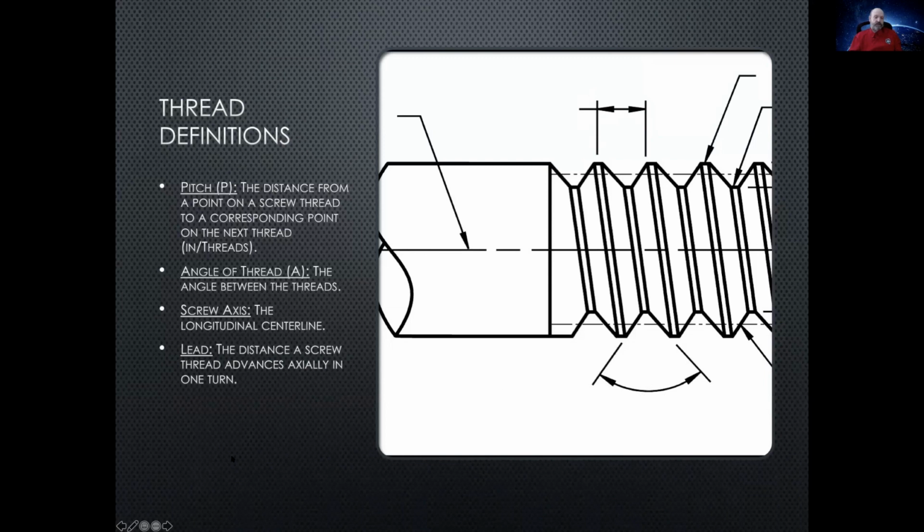So in industry, we used to have to maintain lead screws on our steppers for precise movement of the stages in our photolithography tools. So those screws were called lead screws, and they were very precisely made. The whole point of those was so you can move a large stage back and forth to nanometer resolution and movement. So that was pretty cool.